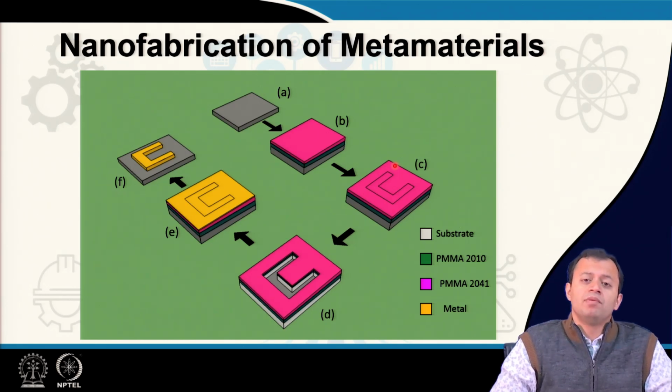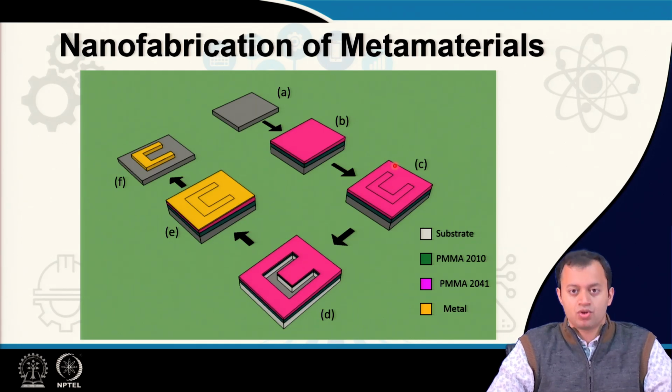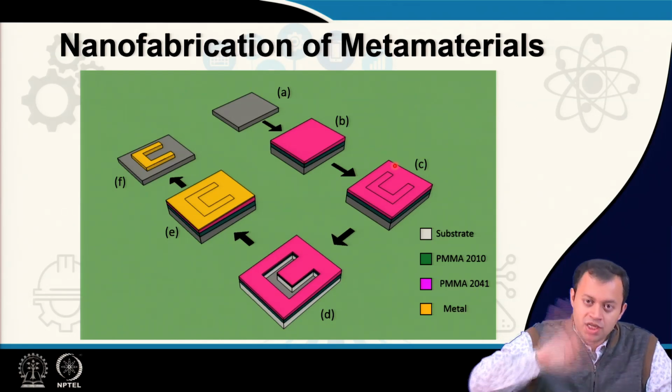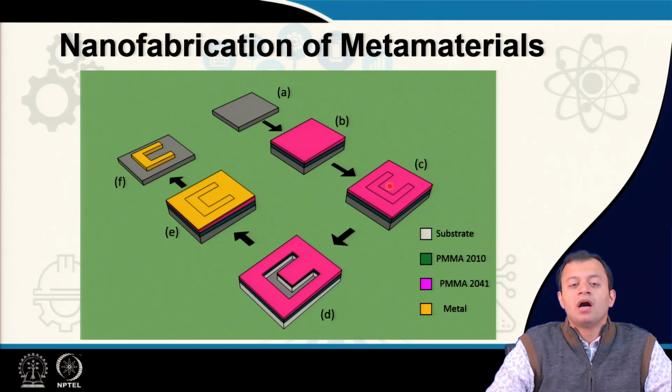So, consider electron beam lithography as a sophisticated and much more powerful, 50 to 100 kilovolt version of a cathode ray oscilloscope, where you can pinpoint where the electron beam is falling. Instead of the phosphor screen, you have a substrate, and you can make the electron fall at an area with a resolution of roughly 10 nanometer. Well, this is nanotechnology, so it has to be at that particular scale.